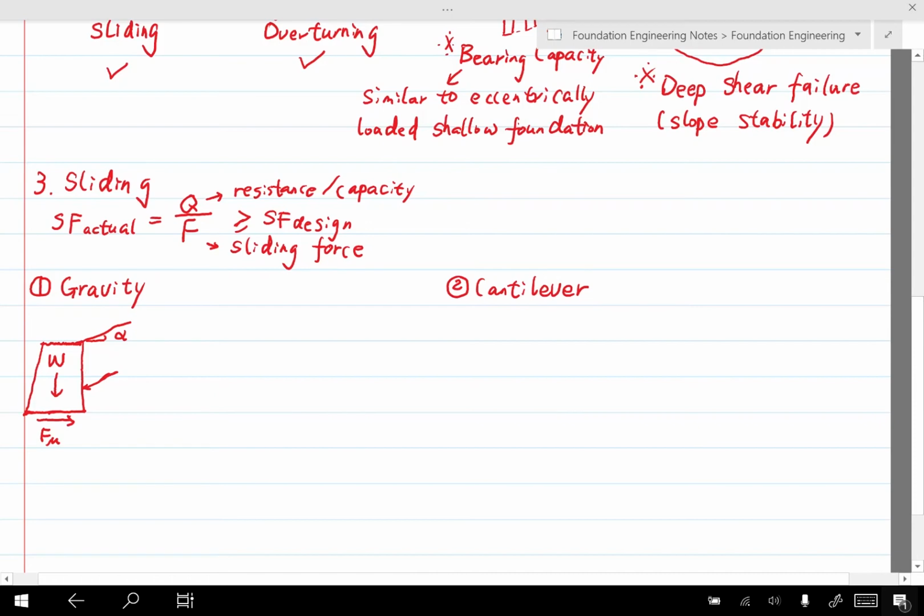And if that's the condition, so what type of earth pressure we would have? If wall moves away from soil, in that case, soil pushes against the wall actively, right? So we have active earth pressure. Accordingly, this force is going to be Fa, so the active force. That's the resultant of the active earth pressure.